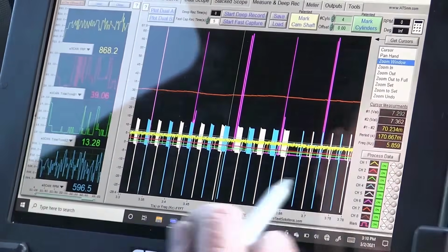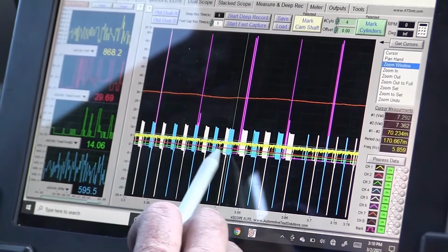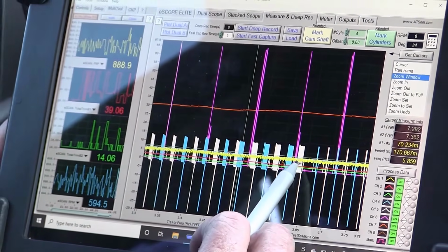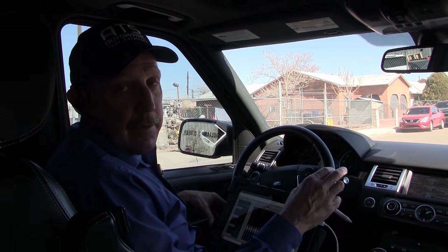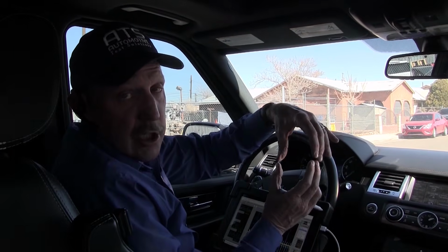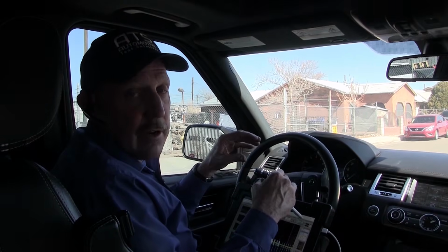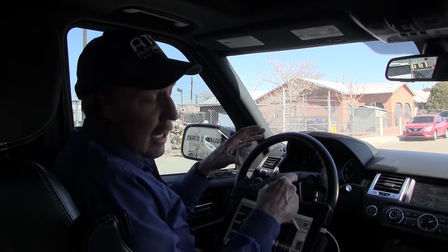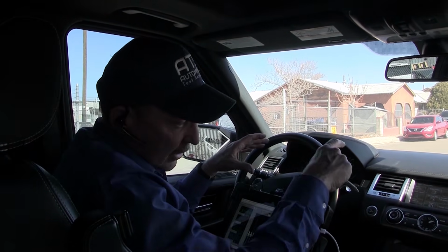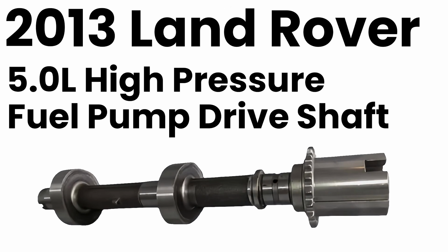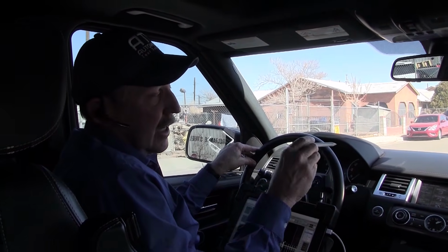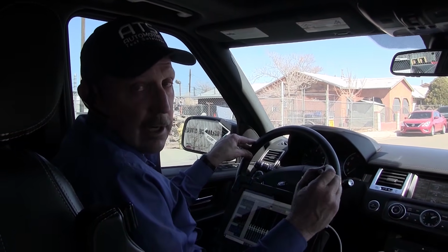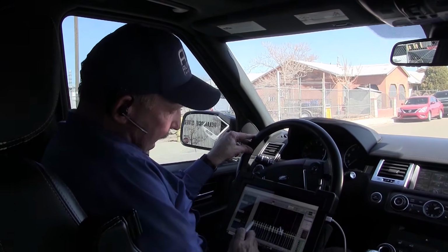So we can see that the pump, do you see how much wider the pump started to drive right here? Now this pump, just so you guys know, there are dual pumps on this engine, 2 high pressure pumps, and there is a jack shaft that each cam has a 2 lobe, and the jack shaft is driven at 1:1 of the crank speed. So for every revolution the crank makes, I have 2 lobes that rotate around. That means that that pressure is going to have an increase each time I have a fuel injector come up to fire. So that's what you see here.